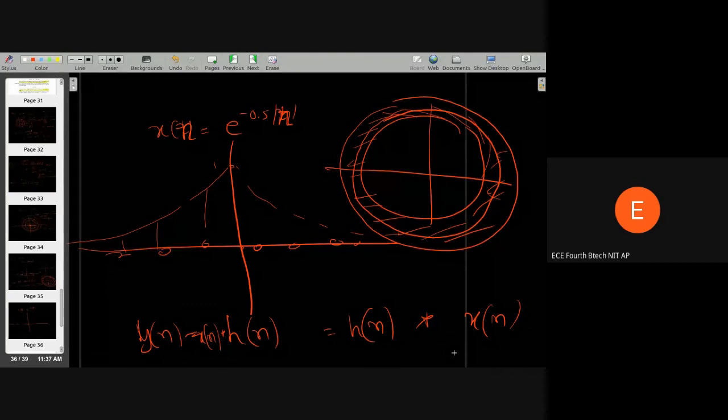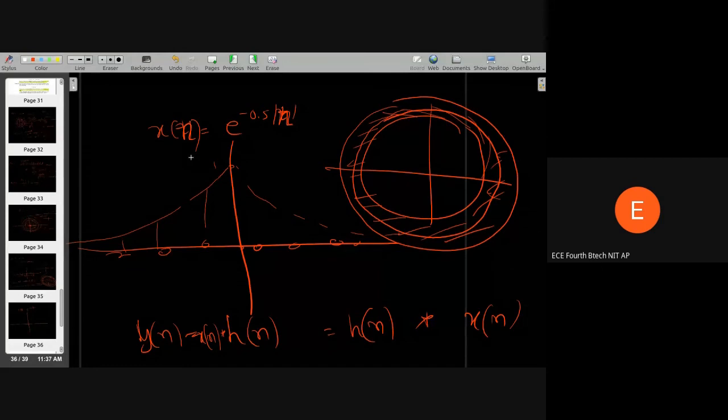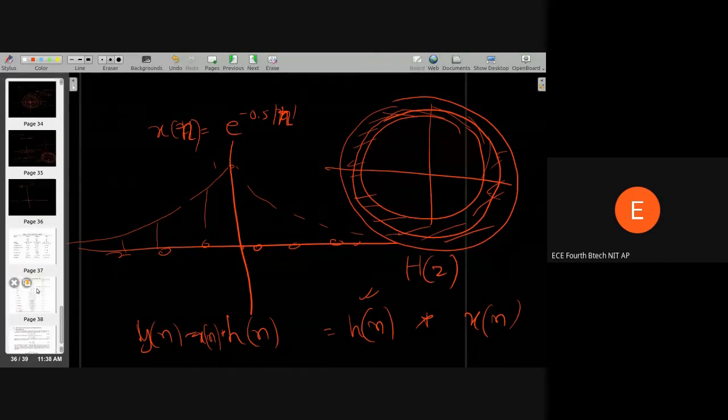I am taking xn here just for illustrating, but with the Z transform, basically we are trying to find out the characteristics from the impulse response. The impulse response that you get, hn, we represent in terms of the system transfer function, which we call hz. We determine the poles and zeros and try to find out the behavior, and analyze the system in the Z transform domain.